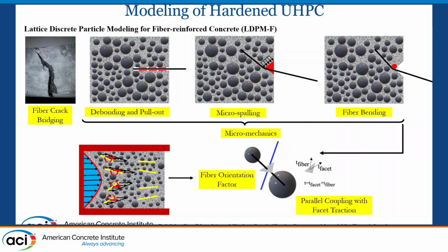Depending on that, you can simulate different fiber orientations and predict the hardened properties. So I predict fiber orientation from my fluid model, coupled with the Jeffery equation and the Folgar-Tucker equation. From that information, I calibrate the fiber orientation factor in the solid model, and from that, I can predict the hardened tensile properties and so on.